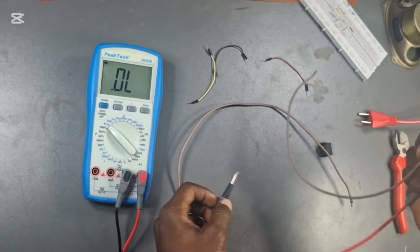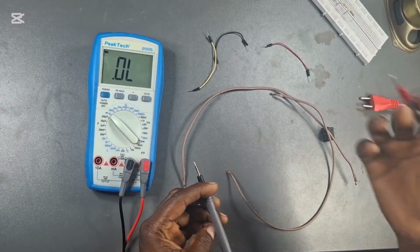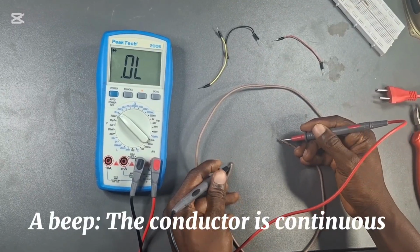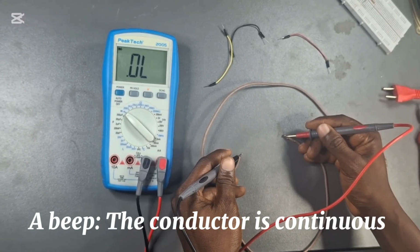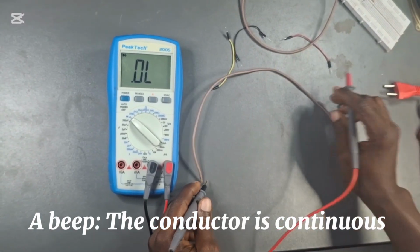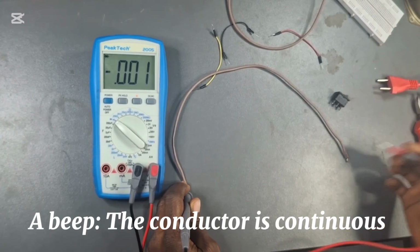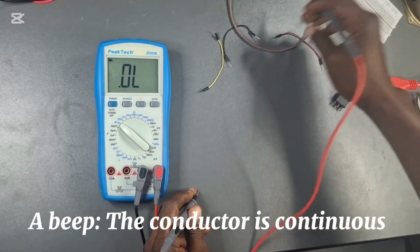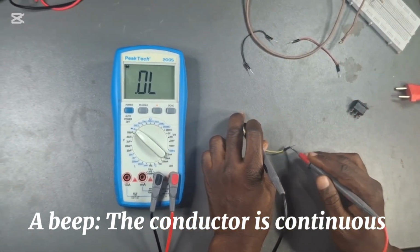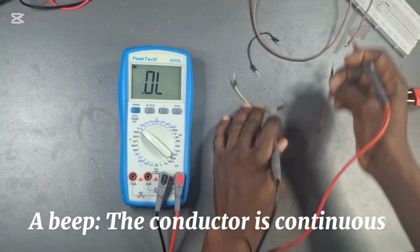Okay, so anytime we take our testing, for a cable to pass, we would hear the sound once again. So let's see. Okay, so this cable has passed continuity test. Let's try this one. Okay, this cable has also passed. Let us try this one. This cable has also passed. Let's try this red cable.